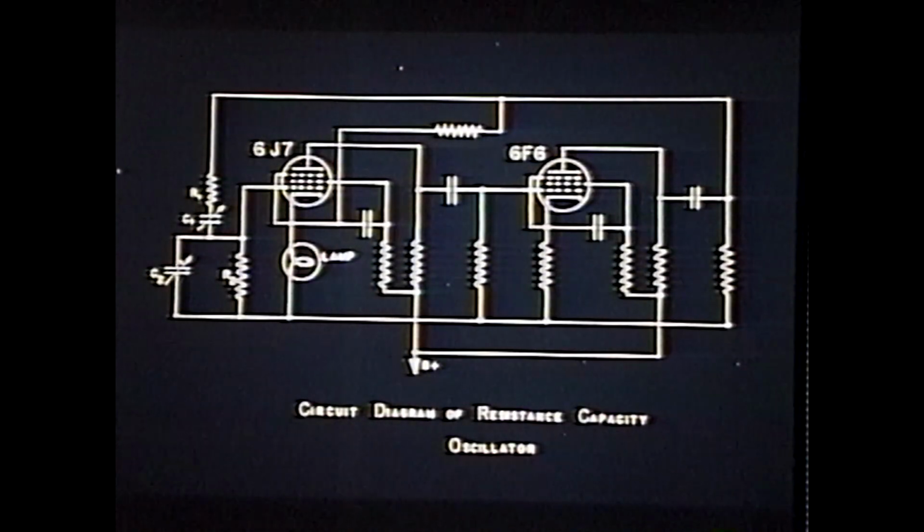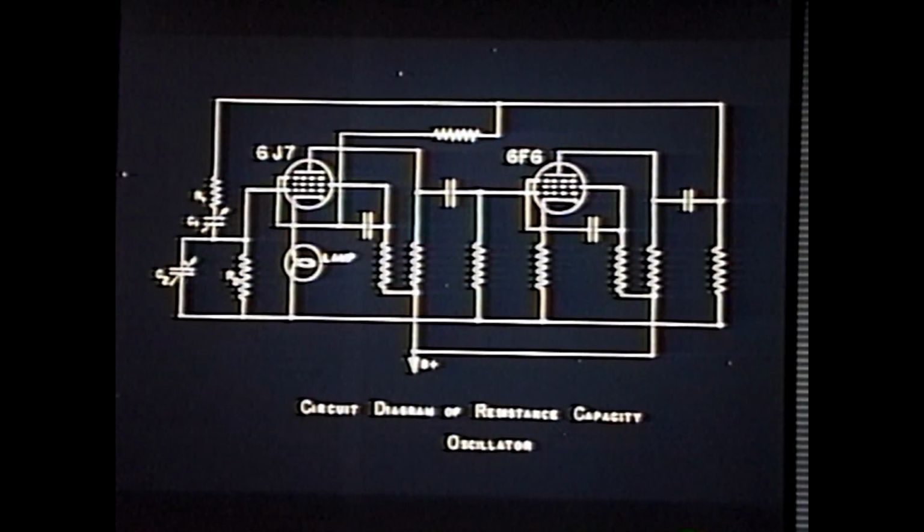This is Hewlett's circuit. This is the original HP oscillator, okay, and this is right out of his thesis. You can see all the elements provided by the authors that he sincerely appreciated. Okay, here's the Wien bridge. So that's one side. He got rid of Meacham's crystal and put the Wien bridge in. Here's the lamp. So that's the other side of the bridge. Here's the output of the oscillator. And where does it go? It feeds back to drive the Wien bridge. There. That's the positive feedback.